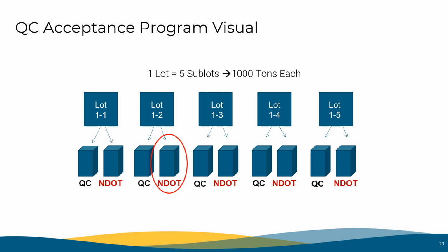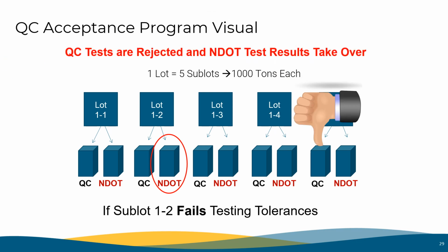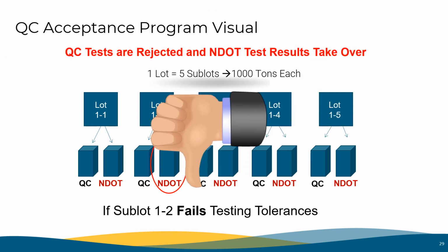If either the air voids or FAA results do not correlate with the NDOT lab results, we will reject the contractor's QC testing for that lot, and they must use the NDOT's results. This will also initiate a full review of the contractor's testing and equipment, what is called an independent assurance, or IA review, by the quality assurance team. The rest of the split sample must be submitted to the NDOT Quality Assurance Laboratory for further testing.